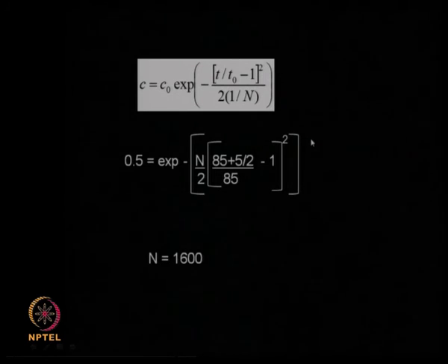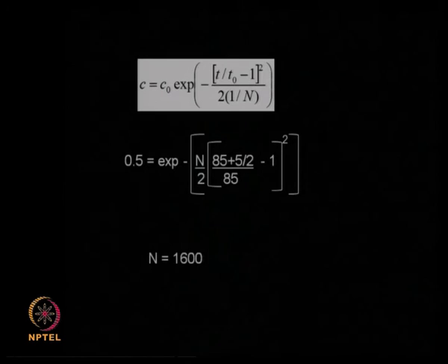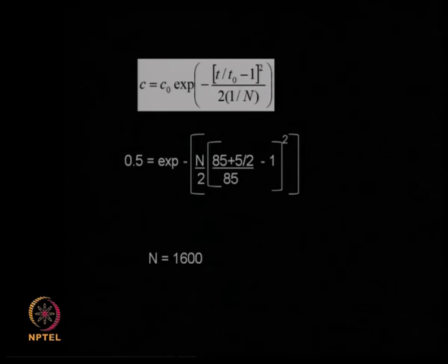Making use of that relation, we can do several calculations, and also by making use of the discrete stage analysis, we are able to develop, just based on mass balance, a relationship between the solute concentration going in and the solute concentration going out, and equate it to the accumulation. And if you assume a linear adsorption relationship, we can get quite a simple relationship between various parameters which can be used for all these types of analysis.